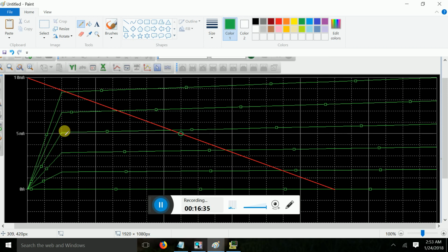What is actually happening is that in the saturation region no amplification can be done, and the output also cannot be more than VCC. Now if VCE is 4.5, then 4.5 minus 5 will be minus 0.5, which is beyond the saturation region. And for the positive half cycle, 5 plus 4.5 is 9.5, which is also beyond VCC. So the distortion is coming.